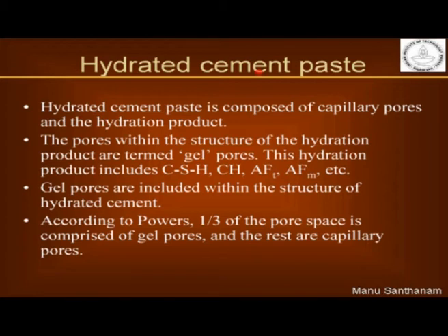Now this is the most important fact, as it relates very well to how your concrete structure finally looks and how concrete finally behaves when it is exposed to different sorts of loading or different environmental conditions. Hydrated cement paste is composed of capillary porosity and the hydration products. You have porosity in the system because when cement hydrates and reacts with water, there is no way you are going to fill up the entire volume with solid. So there will be a lot of porosity, zones not occupied by solid, that is called capillary porosity.